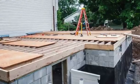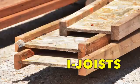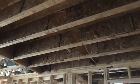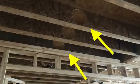Joists used to be just dimensional lumber, like wide, flat pieces of solid wood. But in recent years, engineered lumber has partially replaced them. I-joists are modified I-beams built out of long pieces of strand board and solid lumber caps or flanges. I-joists are cheap, stable, and very versatile. And they often contain pre-cut knockouts that you can run utilities through, like ducts and wiring. This makes later construction phases both easier and cheaper.